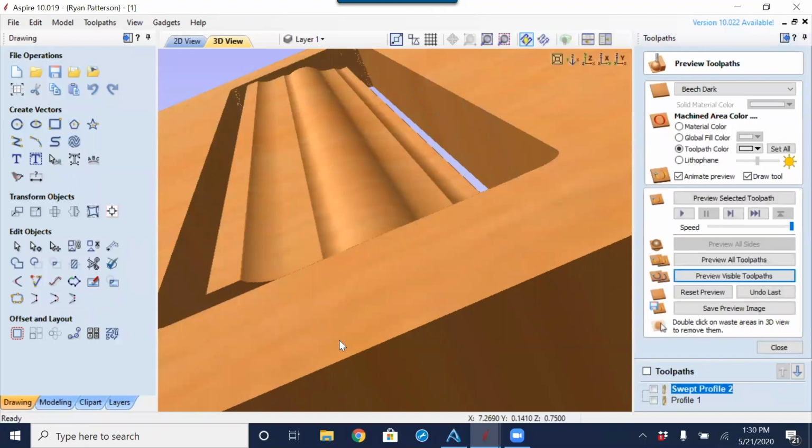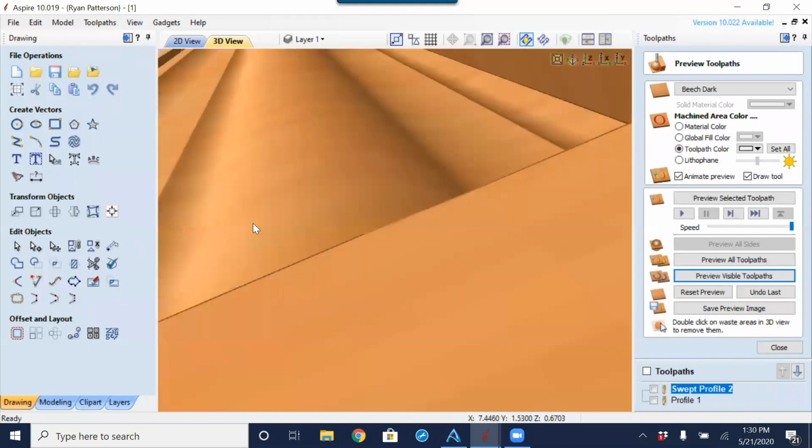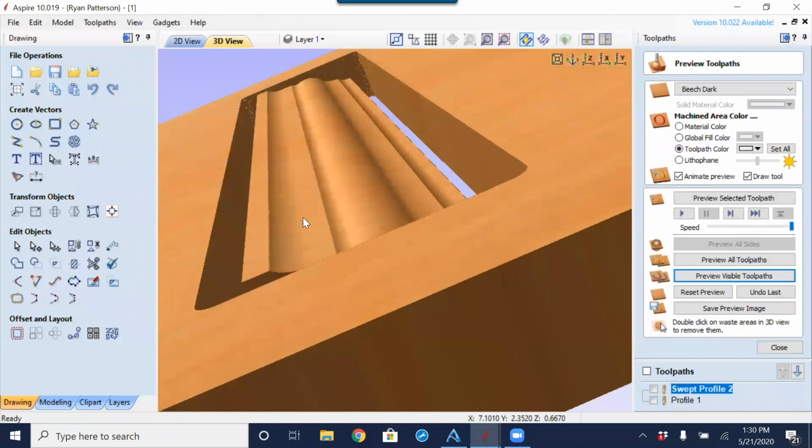So there we can see that the 1/4 inch ball nose will actually end up giving us a slightly better surface finish than that 16th inch ball nose did. Yes, we are very tight on our step over, or our percentage of step over, but it is the same as if we used the 16th inch bit.